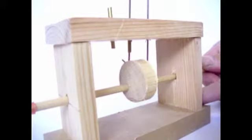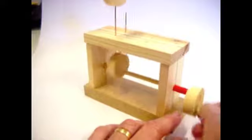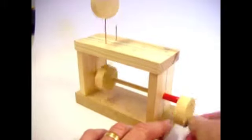There are many cam situations that need to be solved. This one of turning is one example. To stop the follower turning, you can bend the wire where it meets the cam and return it back into the automata box. See how this works.